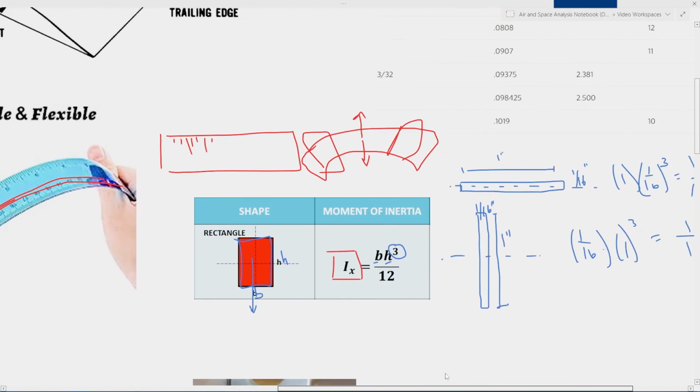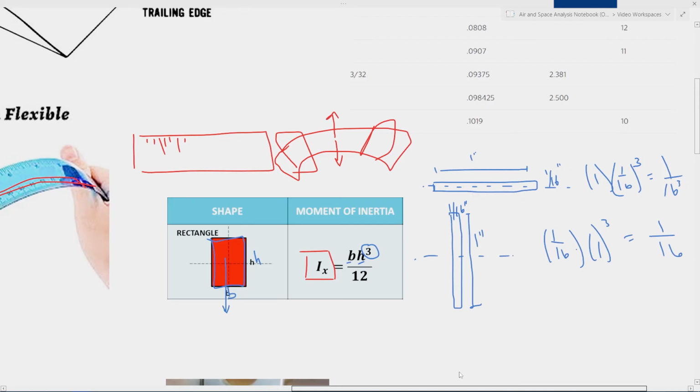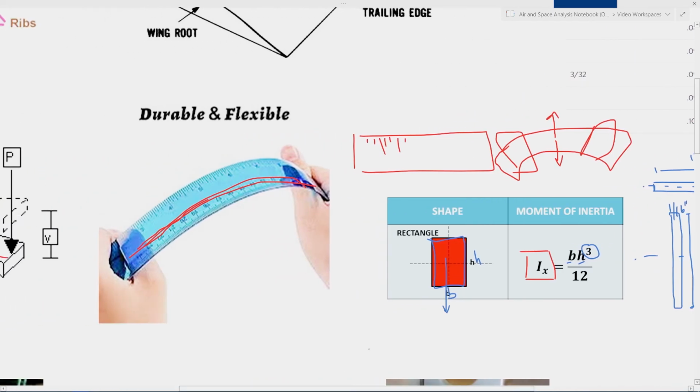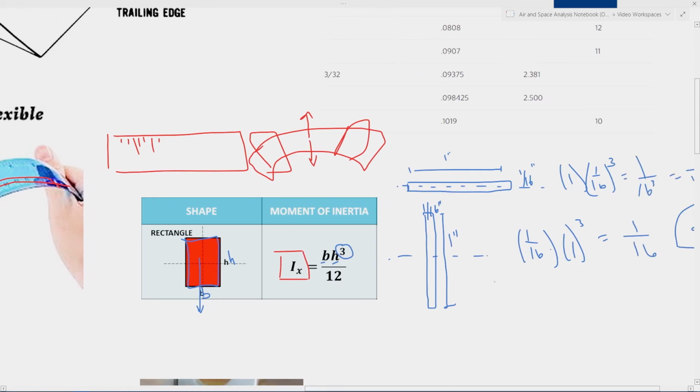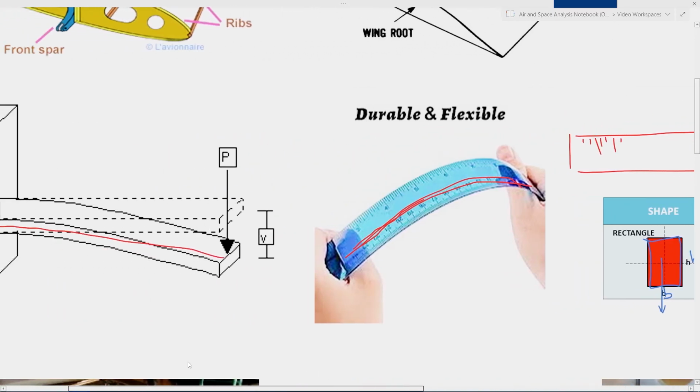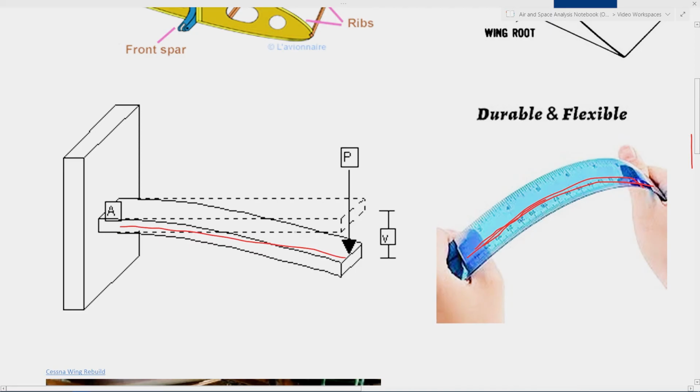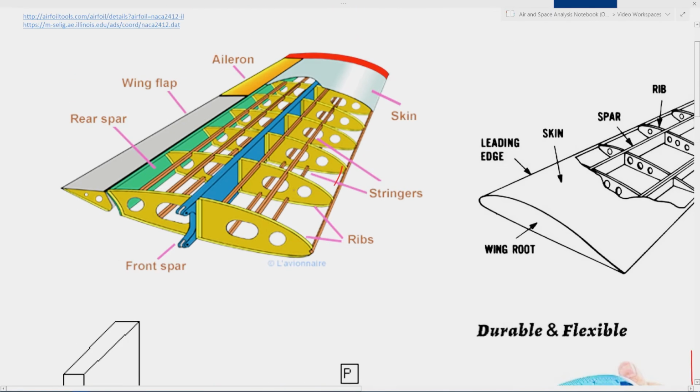So, of course, that tells us a lot about designing stiff structures. You want to maximize your material in the direction that you're going to be bending. So you'll see I-beams, beams that look like this. These are good at taking bending loads because here's their bending axis, and there's a lot of material far away from the bending axis, so they're very, very stiff, right? So hopefully that helped you understand what we need to make a stiff structure.